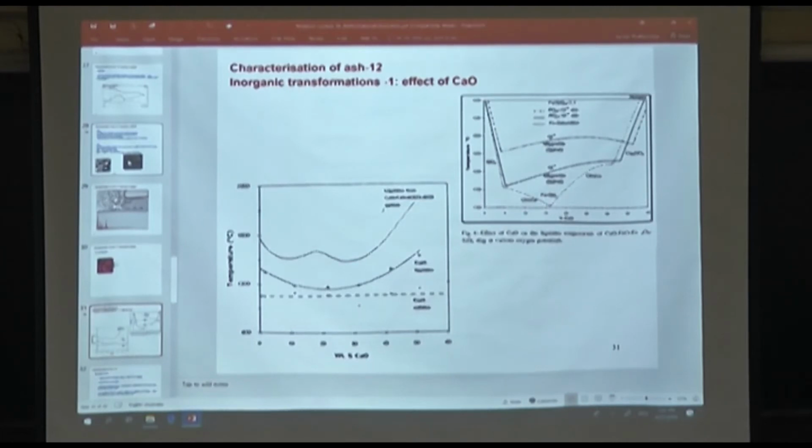How can a particle get exposed to very high temperature when you know you are not running your combustor at that high temperature? As I said yesterday, it is the combustion of the volatiles, right? The five different stages when you subject a coal particle: drying, pyrolysis, combustion of the volatiles, ignition of the char, combustion of the char. The volatiles are very, very strongly energetic gas. They can give you very high temperatures, very high heat release momentarily, which will never be detected by any thermocouples that you insert.